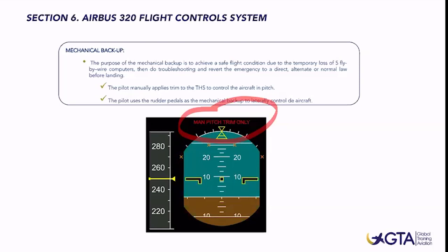Well, the main reason why this flight law is not designed for landing is because the pitch control that the pilot will have available is only the trim wheels, and the lateral control that we will have available as a pilot is only the rudder's movement.